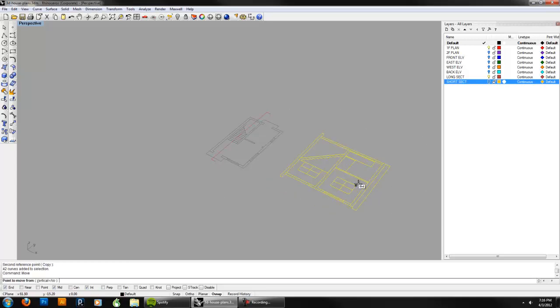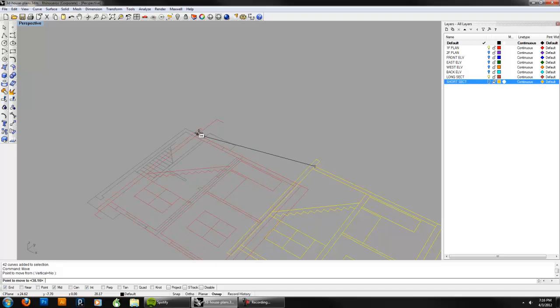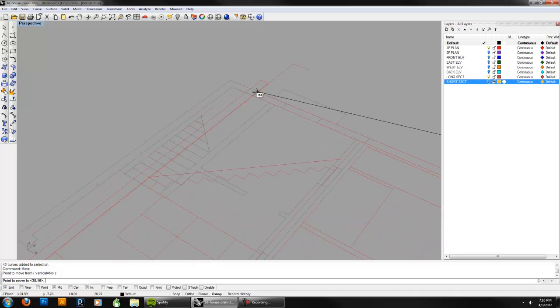move, and you notice that this has kind of a plinth on it, kind of a foundation, so I need to be careful about this when I move this in the x-axis. So I'm going to go ahead and move this here, sorry, in the z-axis, move this here, and I'm going to snap it, and I have intersection snap turned on, so I can snap it there.